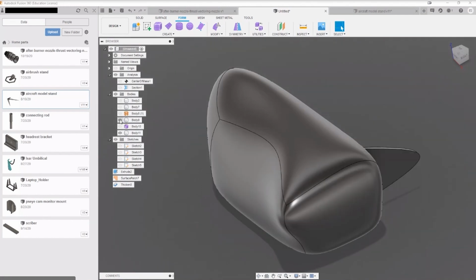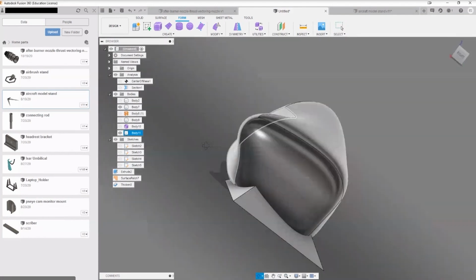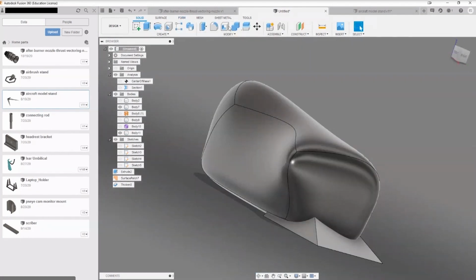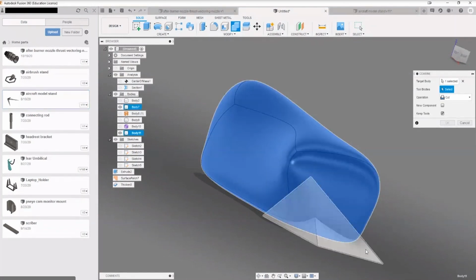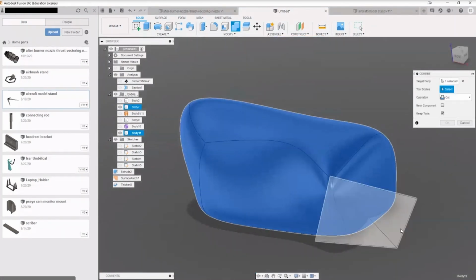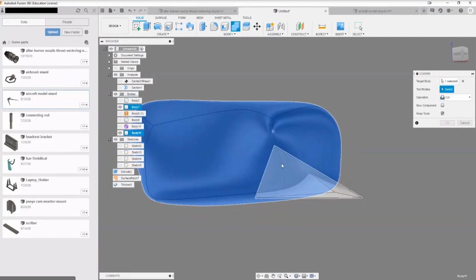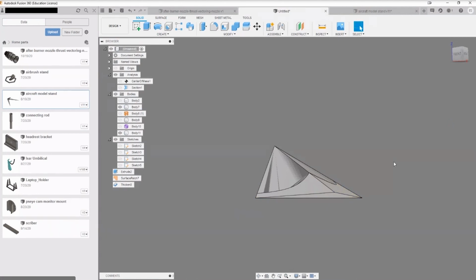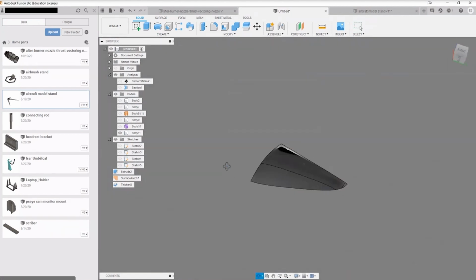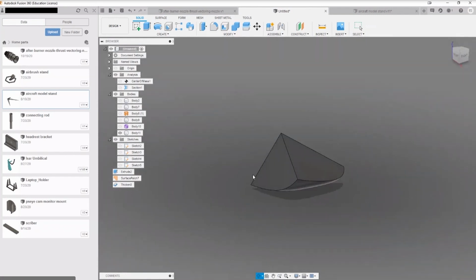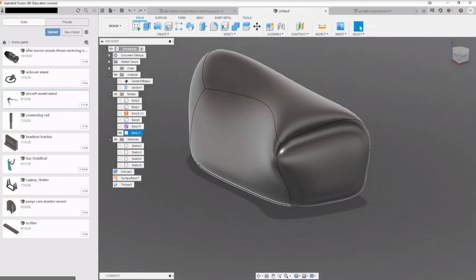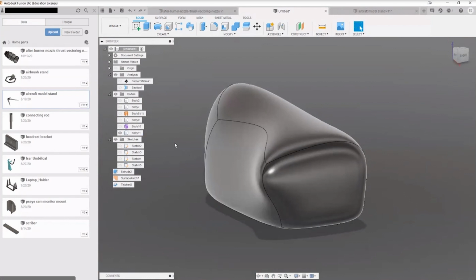And what we can do is select our wonderful triangle creation, and you can go ahead and combine it. And this time I'm going to demonstrate how to use the intersection boolean. So if you want to leave an area that's almost like a 3D component Venn diagram, if you want to leave stuff that's in between the two, you select these, you go to intersect, bam. You get rid of that, and you're left with this one single corner. Very rare that you'd use it, but good to understand how it works anyway.